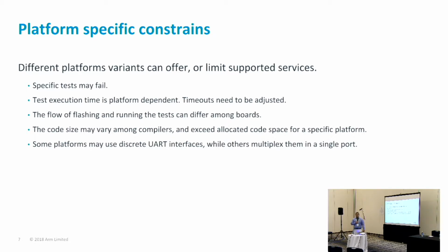Last but not least, there is not a common agreement on how to implement the debugging UART interface. Some of the boards use discrete UART interfaces, some use jumper UART interfaces, some others multiplexing UART interfaces. So you might come across a situation where you are running the proper firmware and not getting any output because the wrong UART interface is producing the output.